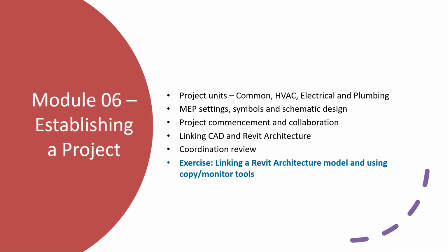Next, we configure MEP settings, symbols, and schematic design. These settings define how systems behave and appear, and they're critical for aligning with engineering standards. We then move into project commencement and collaboration. This includes setting up shared parameters, defining roles, and preparing the model for multi-user access.